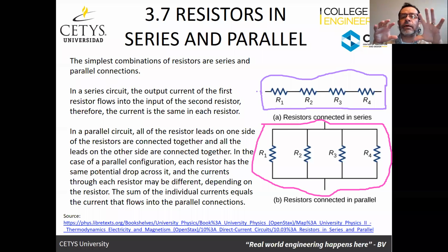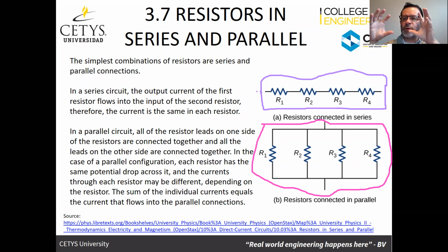If we have many resistors connected in an array, we can calculate an equivalent resistance, which is a reduction of the circuit that lets us analyze its components. The equivalent resistance is one resistance value that has the same effect as all of the resistances connected together in the array.